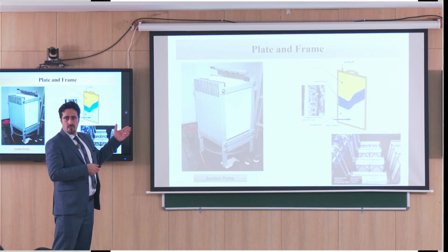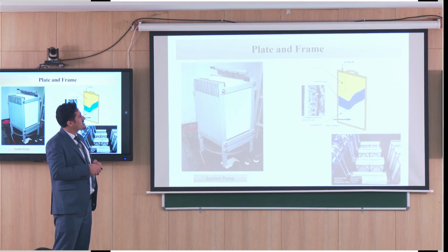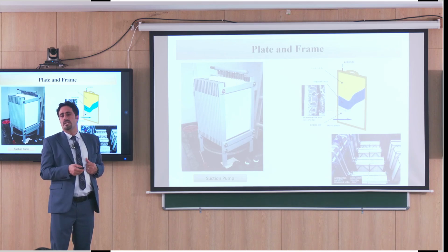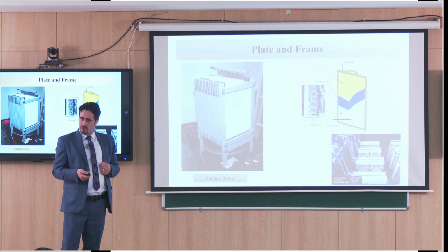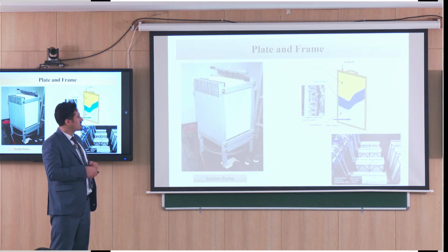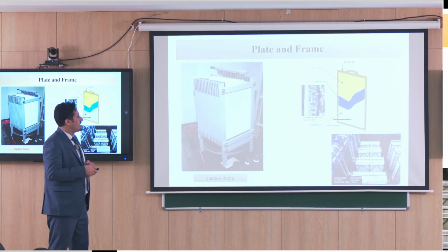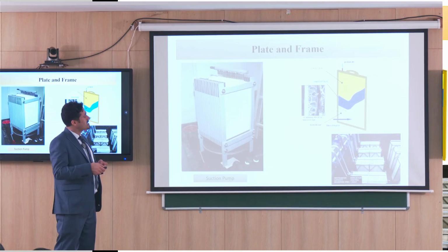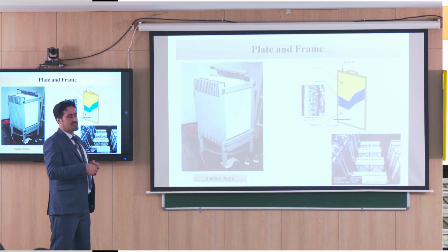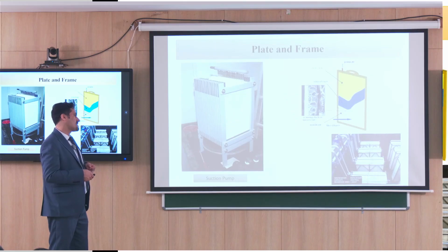with plate and frame modules. This is suitable and mostly used in membrane bioreactors. These frameworks are used in membrane bioreactors for separation of microorganisms from activated sludge and increase of the MLSS, the microorganism mass.